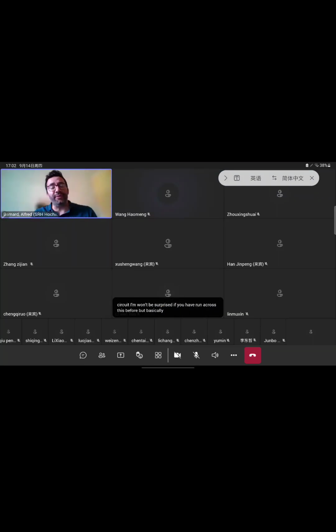Basically, as it does, with the resistive and capacitive elements, as one capacitor is fully charged, it switches on the one transistor and the one LED starts working. As it starts working, the other capacitor starts charging. Then as it's charged, it switches that transistor on, and those two LEDs should switch on and off in a pattern designated by the resistance values and also by the capacitor values. So let's create the circuit and see what it looks like in simulation. I think it's interesting, right?